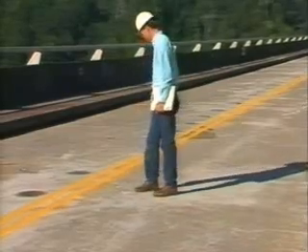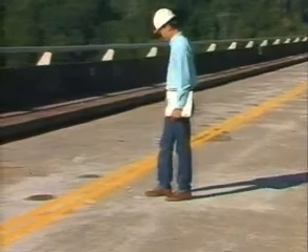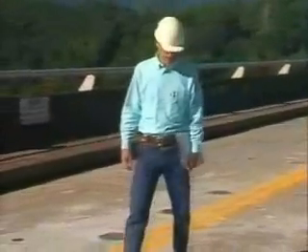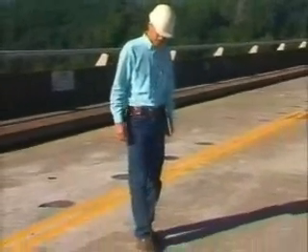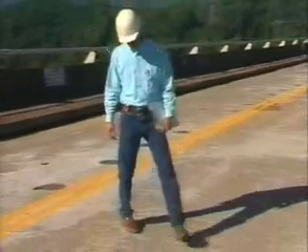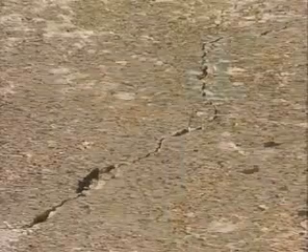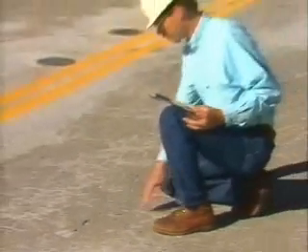As you walk the crest, look for concrete deficiencies such as cracks, surface deterioration, and displacement. The text provided detailed information on these deficiencies in Unit 2. Since some cracking in concrete structures is common, you're likely to find cracks as you walk the crest.